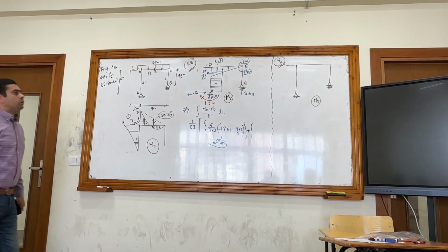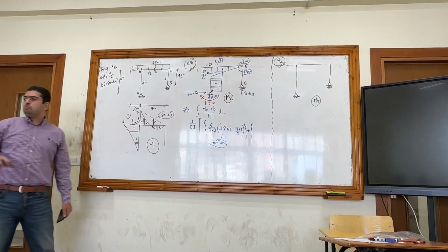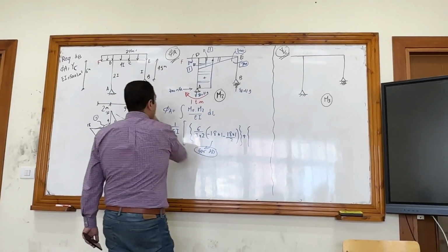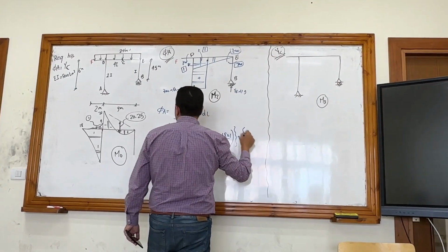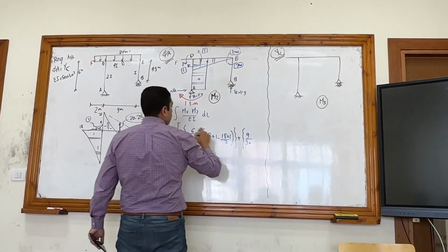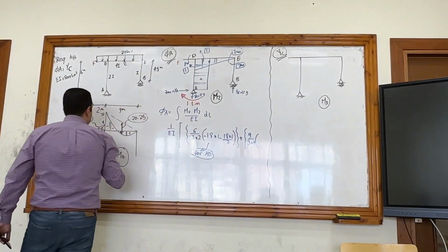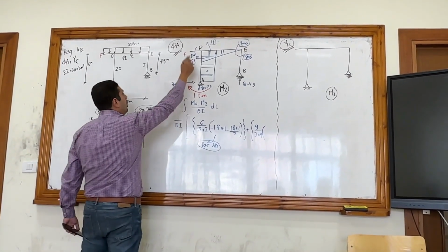Let's start with the first part, the triangle with the triangle, so linear with linear, so the same rule, L, which is now 9 meters, divided by 3 multiplied by the inertia factor, which is 4, and then the first value, which is 22, multiplied by 1.